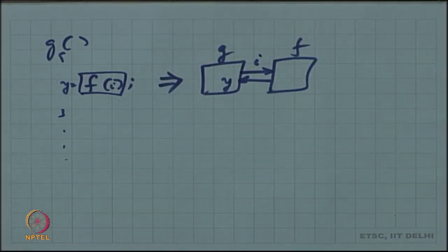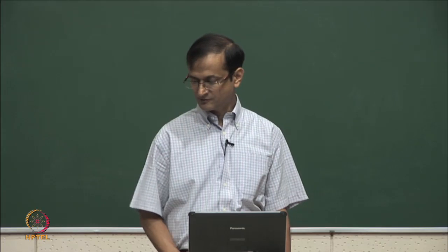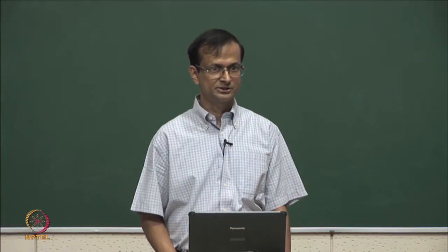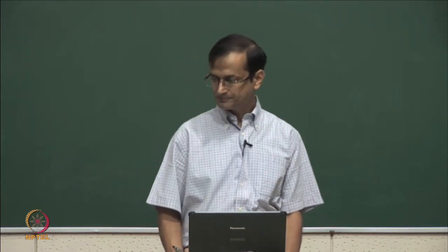If you inline every one of those calls, then it may lead to increased hardware, increased complexity. So, this has to be balanced by different parameters that affect the inlining, but what should just be recognized is that there is a possibility of simplifying the specification by doing an inlining.